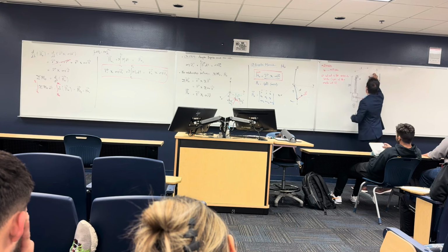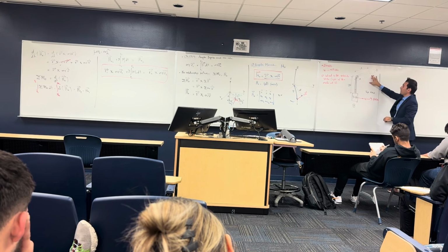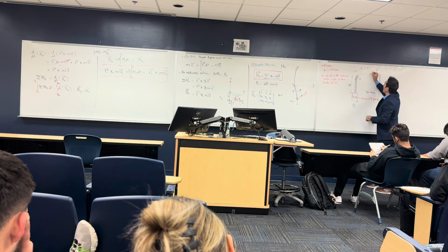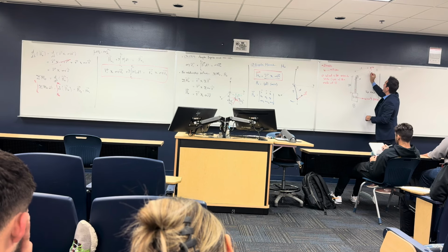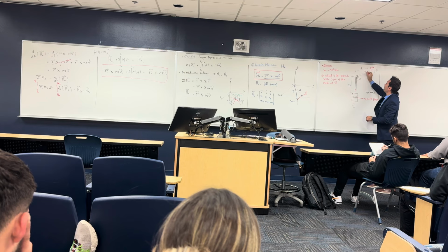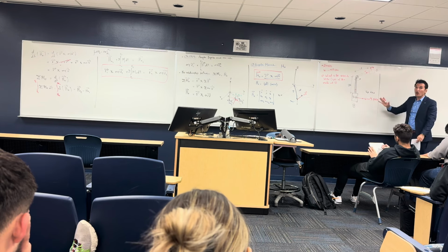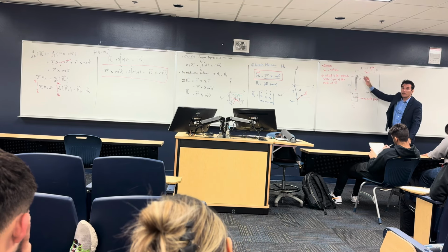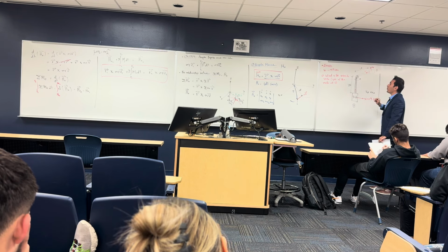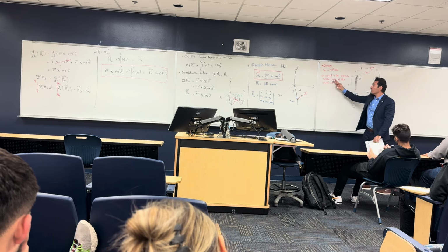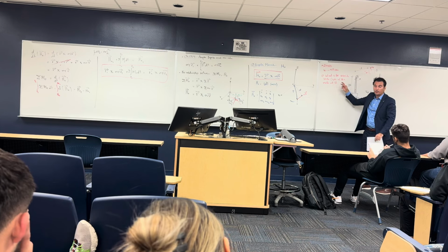So he's asking about the velocity vector. Okay, pay attention to that. So here you are going to have a velocity this way, v theta, and a velocity this way, vr. Because this arm has two components. This arm is shortening, and at the same time, it's moving this way. So we need to find these two components. And it's an r theta problem because that's what I'm asking for, r and theta, right?